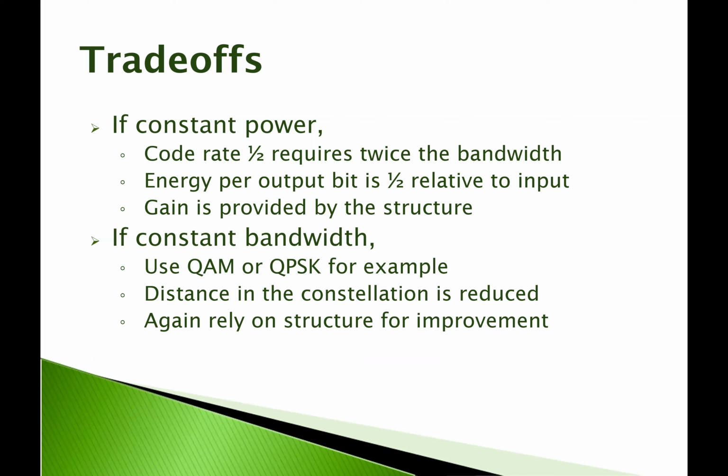So now we can encode that to a particular constellation point, QPSK. When we don't have a number in front of it, it means 4, all right? So the quadrature Q implies there's 4 constellation points. And so we can encode 2 bits into one of those constellation points, right?